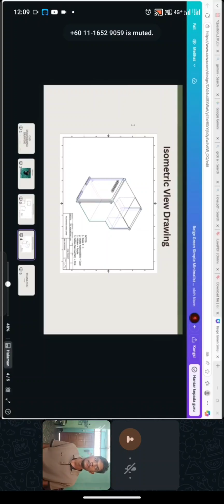We organized our CAD drawing using a layering system, which is very important to maintain clarity and control. We created layers for outline, hidden lines, center lines, dimensions, hatch, notes and annotation. Layering allowed us to switch on and off specific groups of lines when editing.